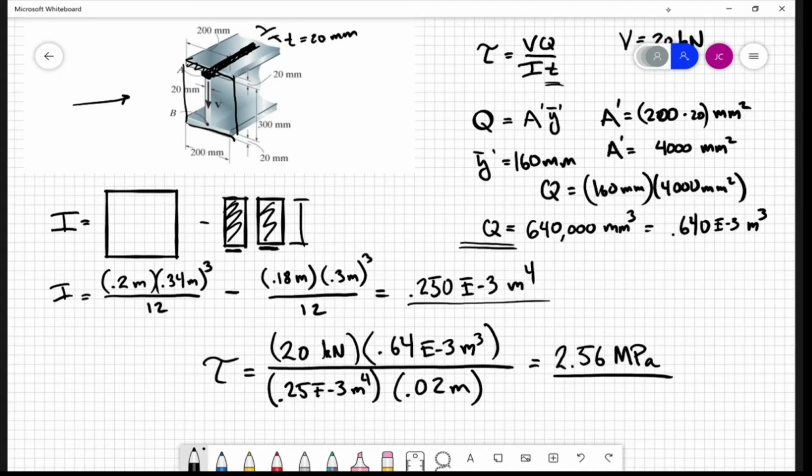So you can't just look at a beam and say, okay, what's the transverse shear stress due to bending? You have to say, what's the transverse shear stress due to bending at this plane, a distance 10 millimeters from the neutral axis or something like that, all right? Okay.